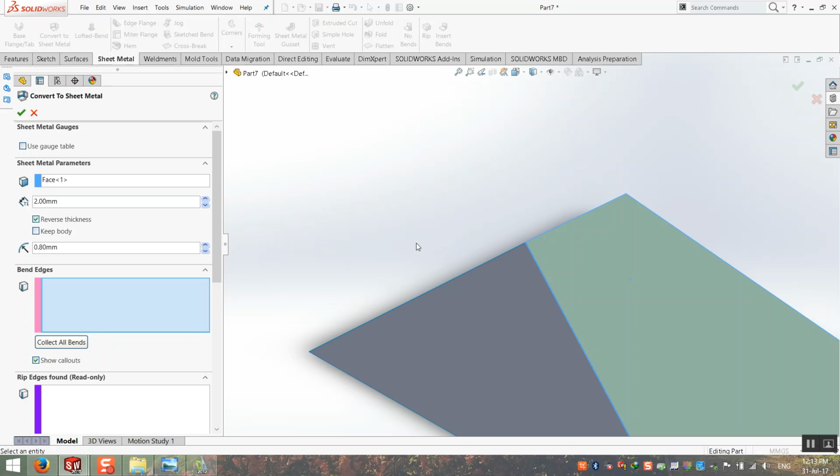Because in design you should put here the bending radius based on the document of the machine. So it tells you when you bend, what will be the radius of that bend, based on the thickness and the type of material. It's very important. Also it affects flattening. When you make a planking, finally for laser cutting, we discussed together and we showed already that when you change the radius and k-factor, it changes the planking size. You will not have the same dimension.